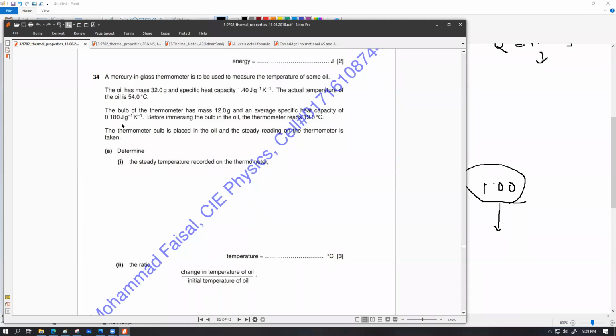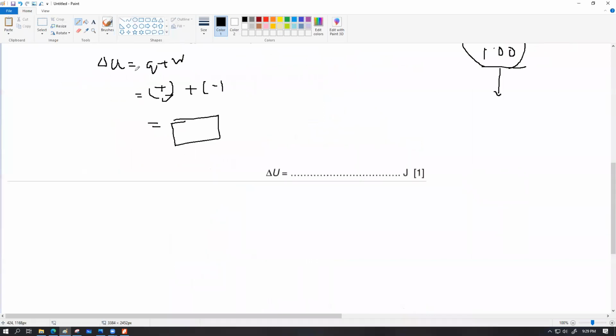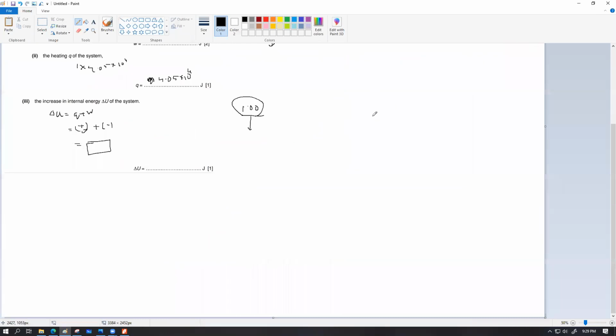Okay, got it. In this case, by mentioning the word bulb, the bulb of the thermometer does not necessarily mean just the glass. Let me show you where I was confused. If I draw a highly magnified view of the bulb of a thermometer, it might look like this. This is the bulb, which produces the thin capillary segment we call the bore. Here the glass wall is pretty thick, which is the stem, and on the bulb the glass wall becomes pretty thin, so that the heat transfer process is actually quite fast. That's how a thermometer is essentially made.